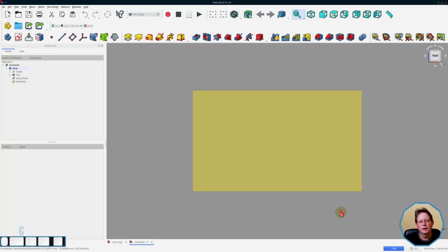As its name suggests, a local coordinate system is specific to a feature in the model. Two examples of this are sketches and datum planes. I'm going to use the datum plane that I created earlier just to illustrate the principles of the local coordinate system. The local coordinate system works the same regardless of which plane or view that you are working with. The x coordinates are horizontal across the bottom of the datum plane, and the y coordinates are vertical up the screen. The z coordinates go in and out of the screen, so it's much like using a piece of graph paper. You can see this behavior whenever you are editing a sketch.